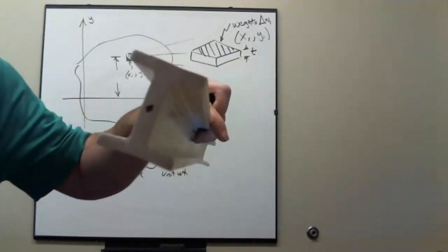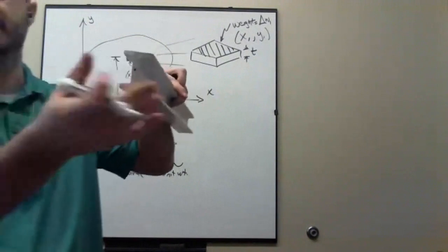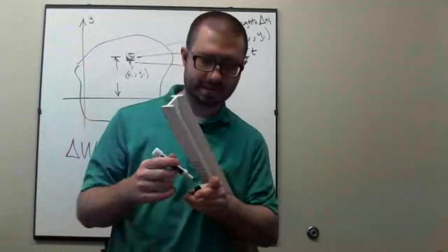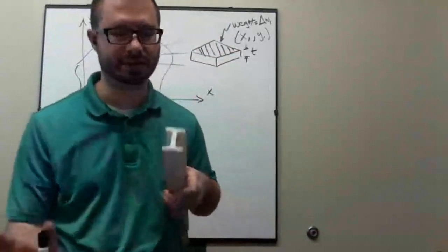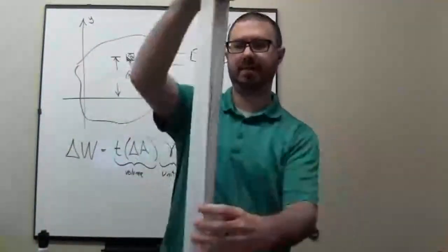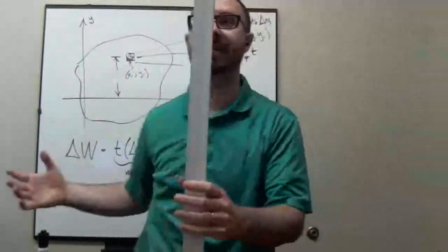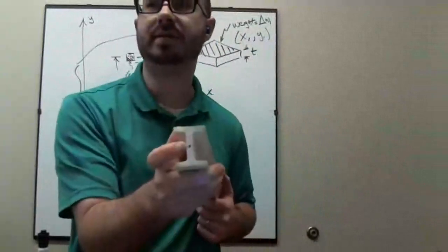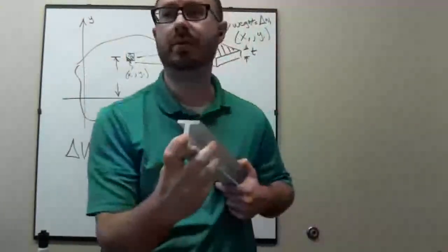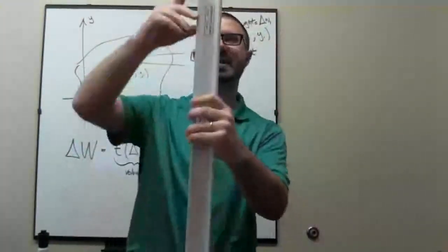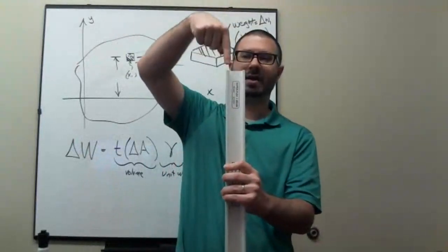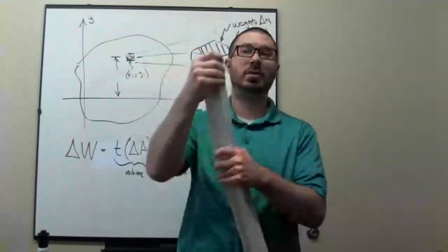And I think that makes sense. It's just the middle of the shape. I mean, it's symmetric. That's pretty simple. Okay, why does locating the centroid matter in an engineering application? Well, if I have this I-beam, and I'm pushing on it like it's a column in a building, if the load goes through the centroid, then I'm not bending it. I'm just pushing on it. But as soon as that load goes away from the centroid, so in other words, instead of loading it directly on the centroid, I load it over here, as soon as I load it away from the centroid, I start to bend it.